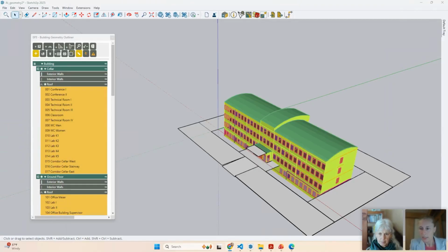So we have a question about the capabilities of EP3 in regards to automatic geometry creation from non-structured data, so 2D drawings, project specs, etc. We can take a 2D floor plan and generate an EP3 floor from it. The quality of the output that you're going to get is dependent a little bit on the quality of that 2D floor plan, so that would be like a DWG or DXF file. It depends a little bit on the quality of the floor plan.